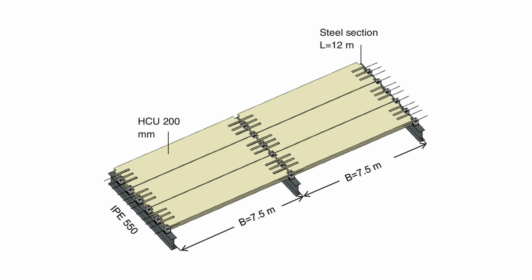For seismic conditions, we have to give certain reinforcement there, which can be done in the screeding as well, or by opening the cores, which are the holes, and filling concrete there. That is what I'm talking about. Hollow core where we fill it on site, but it happens only in the plane portion, not in the slanting portion, because the story differs there.